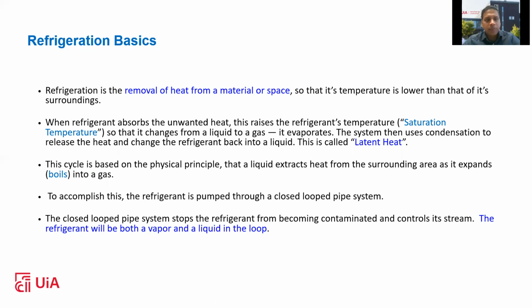The cycle is based on physical principles: it extracts the heat from the surrounding area, and the refrigerant expands or boils into a gas. For example, I don't know if you have seen this in a refrigerator at your home. They have their own refrigerant, which has its own boiling point, or saturation temperature.